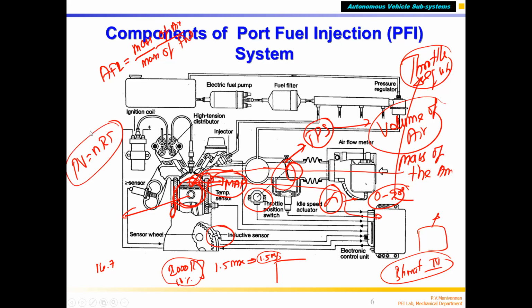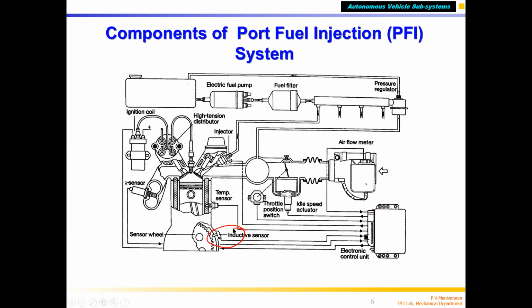Ideal gas, correct? Where pressure, volume, and this is the constant, and of course this is the temperature, correct? Atmospheric temperature varies. So now we need to measure temperature also. If you want to control accurately, you have to measure temperature also. Apart from measuring engine speed and throttle position, TPS, you have to put a MAP sensor to measure pressure. So you can still accurately control, instead of just TPS and speed sensor alone, which is the N-alpha method. You can measure inlet air pressure.